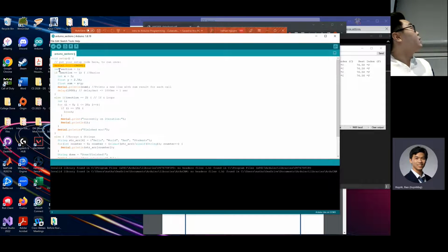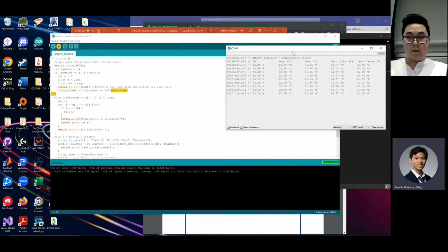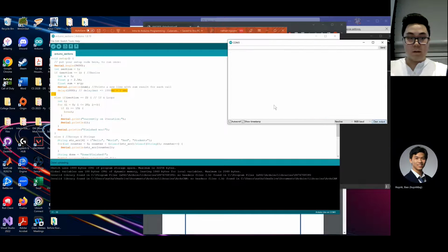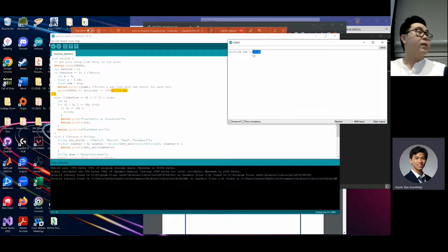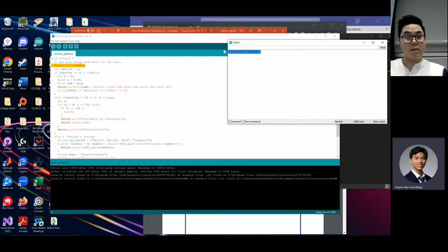And so I set section equal to 1 since I'm doing different sections in one program. This is the example I showed you guys earlier, an int plus a float in a serial output, and then delaying it. Actually, I don't know why I have the delay in here, but just delaying it. And so if I just upload this straight into my Arduino, you can see here that it outputs 7.56, which is your expected value. And so you always have to start up with Serial.begin to make sure that this always outputs into the serial monitor.